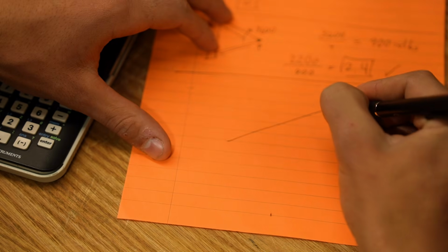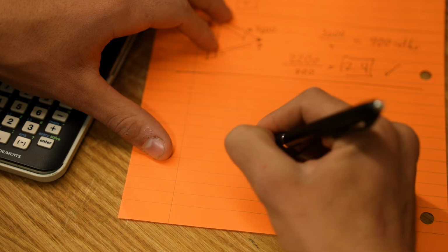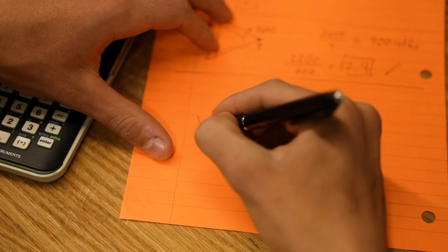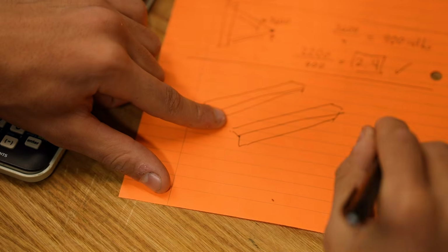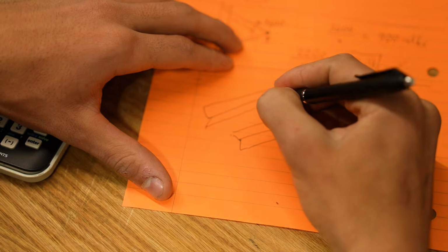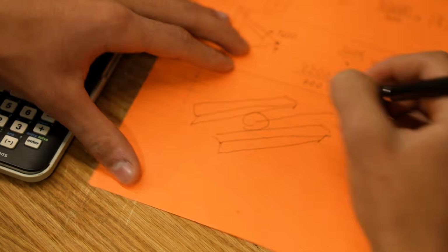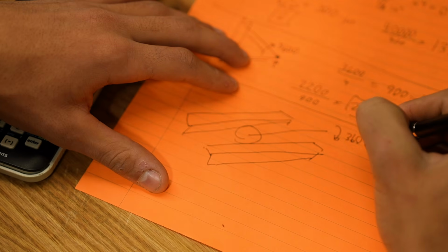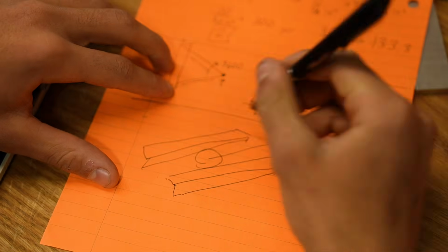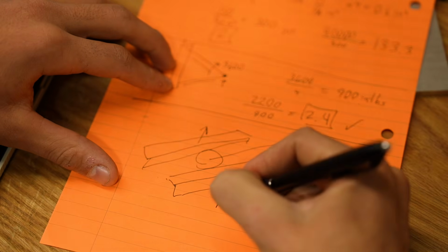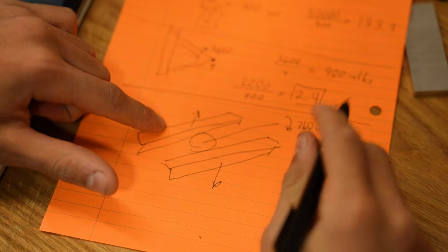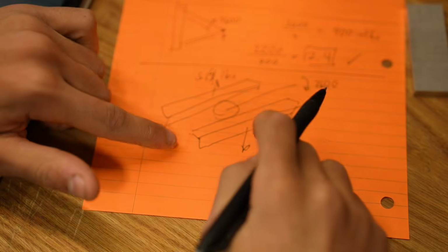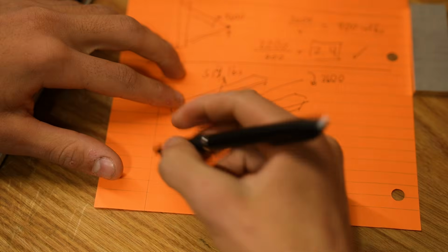So the torque assembly is comprised of two long beams that have a rotational member in the middle, and then those have our post. Our post, again, is driving against that at 3,600 inch-pounds. This creates a counteracting load in each beam across them of 513. So again, we want to figure out what profile will have the correct bending moment to resist that.